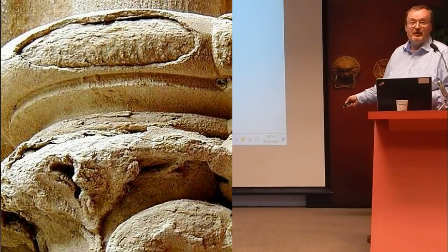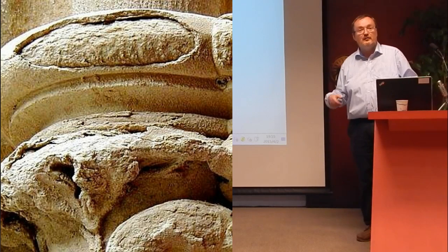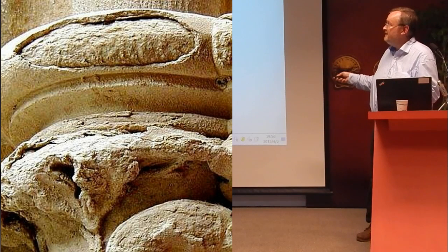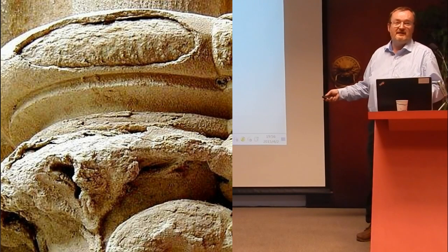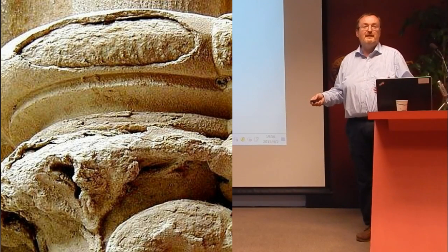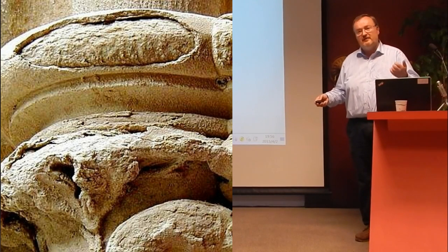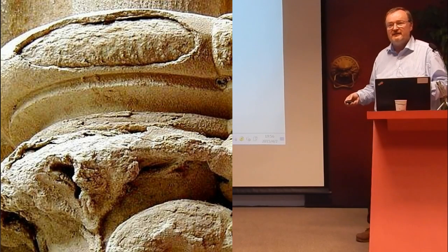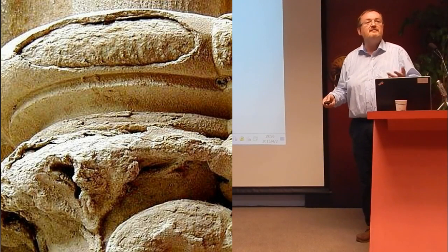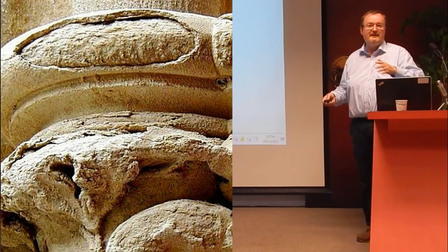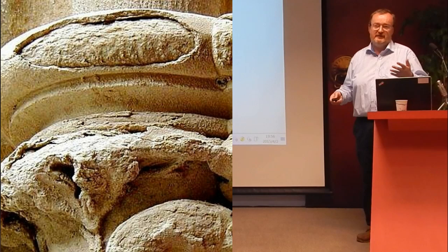A very common problem is to fix a corroded surface of the material at the facade. And this is the way the industry gives us. It is industrially made fixing material. It's siliconates, it's silicates, and acrylic substance, and it doesn't work. I can say from research over many years, it does not work.